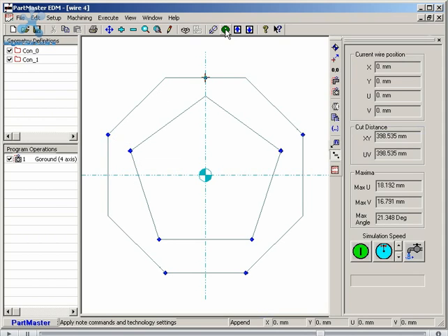And then when I'm finished with that, I simply simulate the job, and now you can see what's happened. I've forced synchronization points between the bottom and the top contour at these positions. Now, because of the nature of adding synchronization points, if I need to change any of those, I have to redefine all of them. And that's because if I tried to just pick up certain points, then the system wouldn't be able to calculate accurately where the synchronization points needed to be.